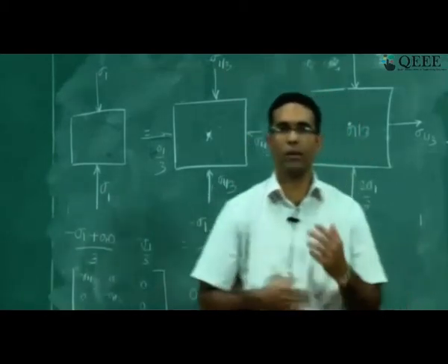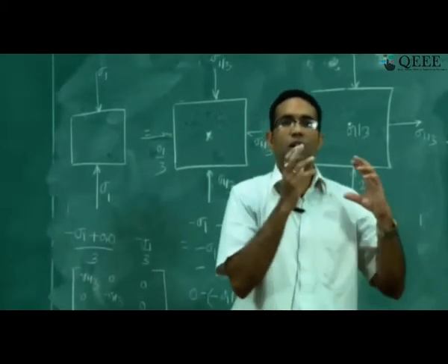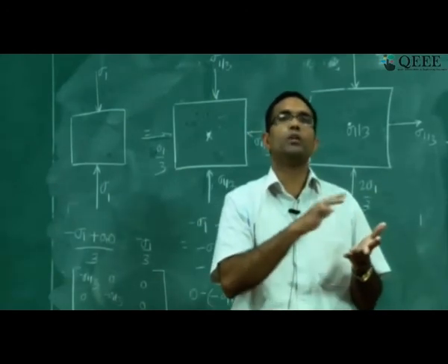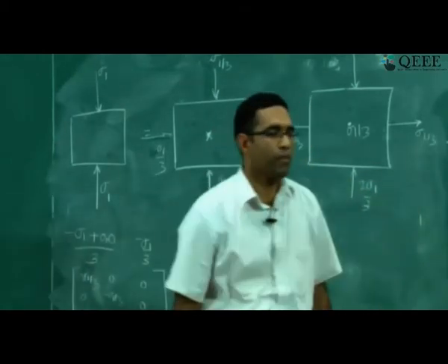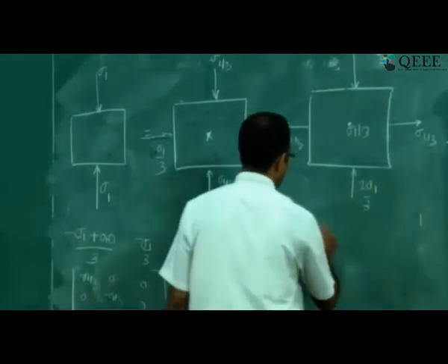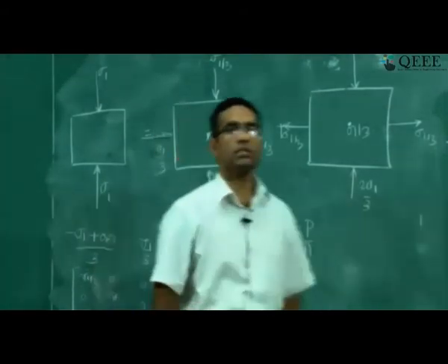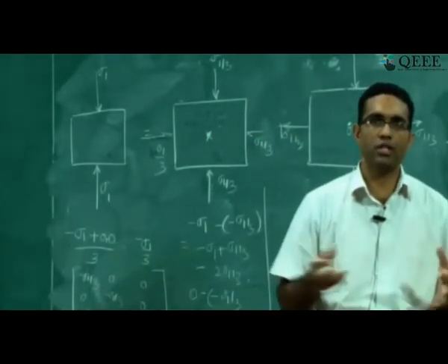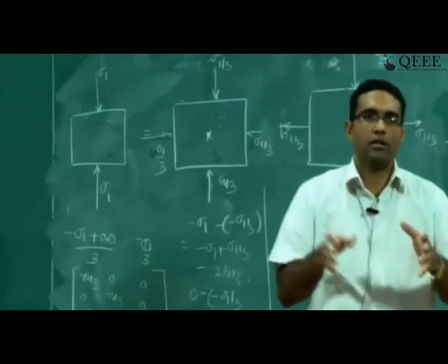So far we have been discussing only stresses. We know what it means to say stress components, deviatoric and hydrostatic stresses, how to find principal values, what is meant by invariance of a stress tensor. All these things we have some idea. Now we talk about strains. Stress is independent of the material for a given loading, it is just force by area. Strain is nothing but change in length by original length, also associated with geometrical changes.